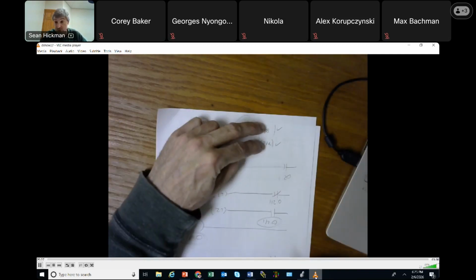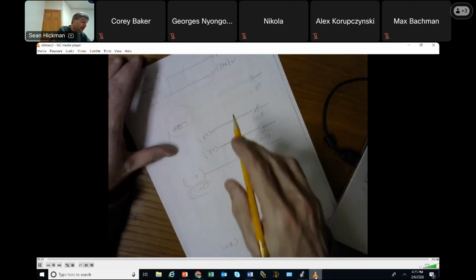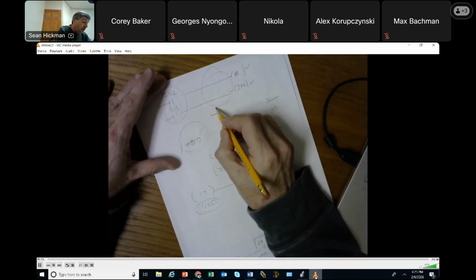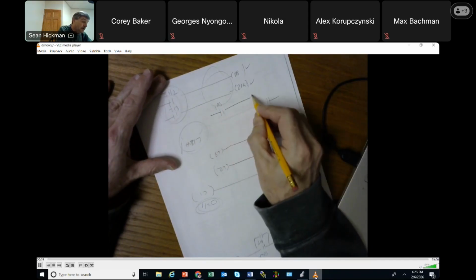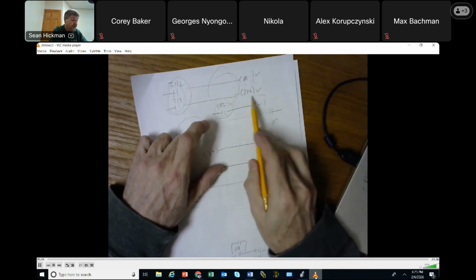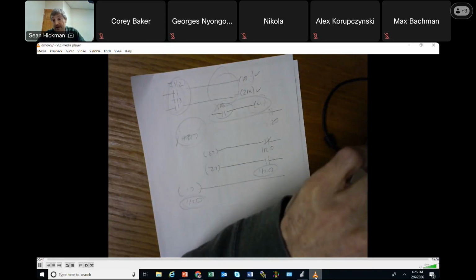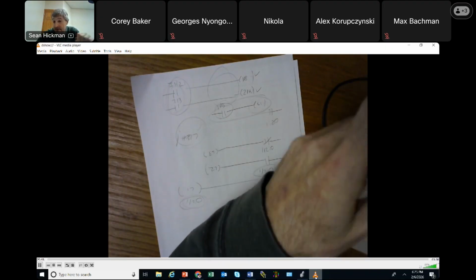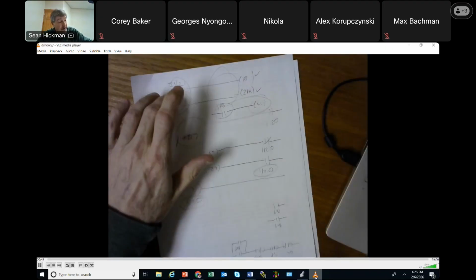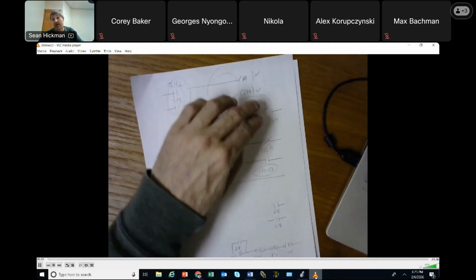I've got all these fictional bits, and then when I write my ladder logic, I say, now I got 1 PB turning on light 1. Well, this scan is fictional. This output is fictional. I took the inputs and I synchronized them up to the same scan rate as the ladder logic scan because these bits are fictional. So that was what we learned.